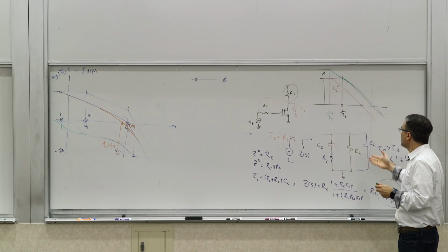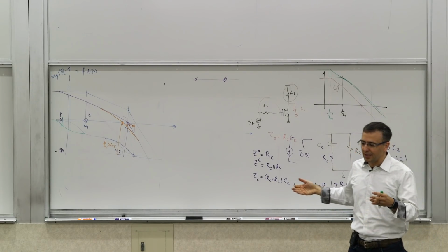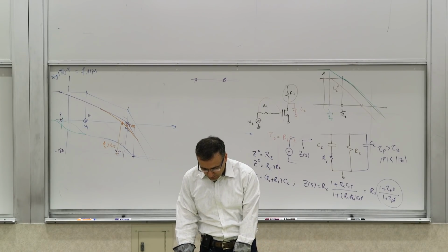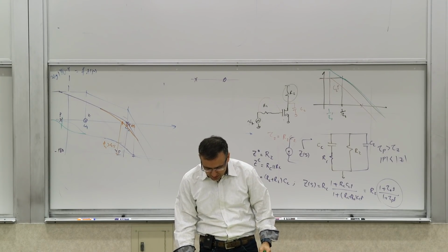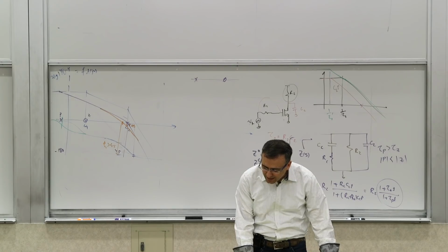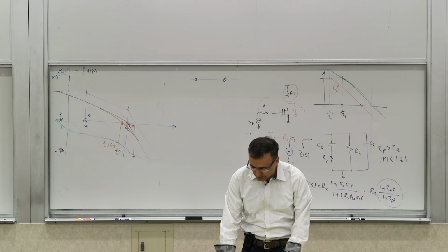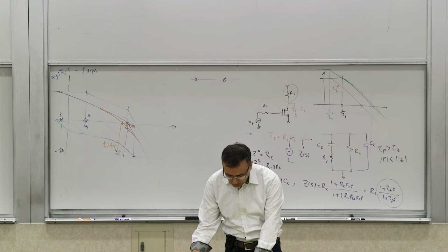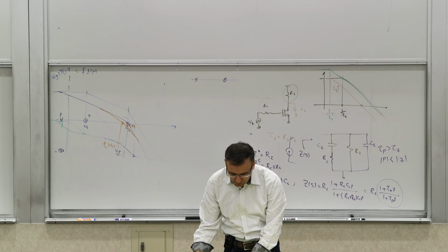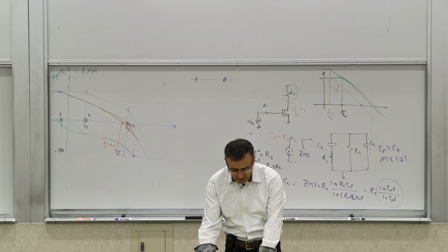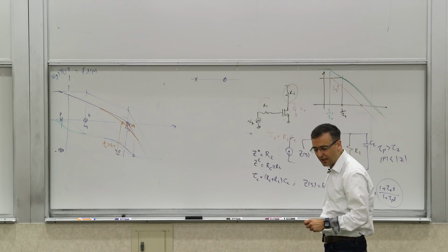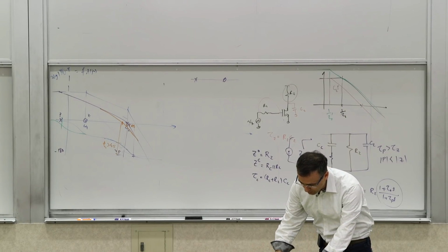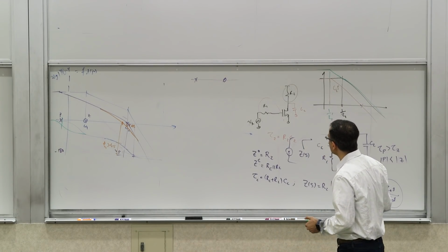Okay, so you can actually make these networks more complex, and people can knock themselves out, but sometimes it's just not useful beyond a certain point. So now let's look at actual op-amp circuits, some of the op-amps that we've designed and looked at before from other perspectives. Now let's look at it from a stabilization perspective, meaning that we want to see what happens to their frequency behavior, high frequency behavior and stability as we go forward.